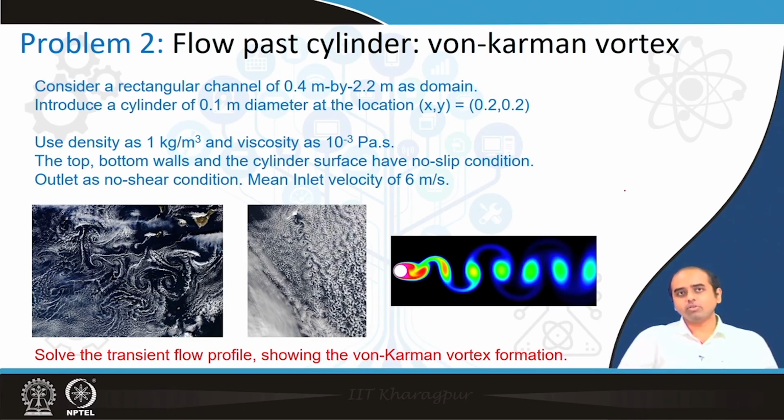On a small scale, these instabilities in the flow, or flow vortices, are formed whenever there is flow past a cylinder at a substantially high flow rate. Near this region there is formation of vortices and this instability initiates, and zones of high and low pressure are created along the channel at the inclusion of any obstruction in the flow path.